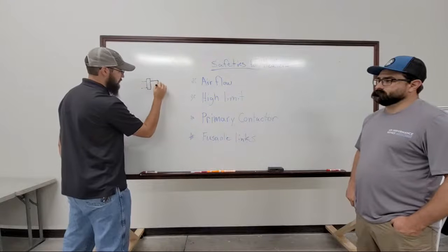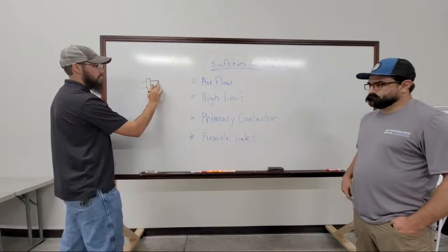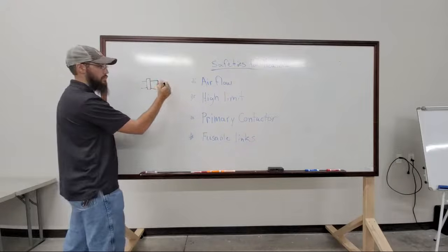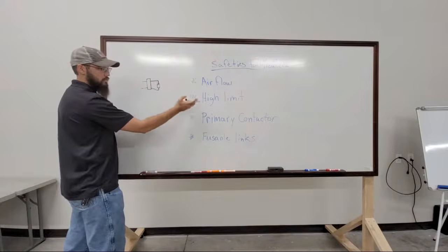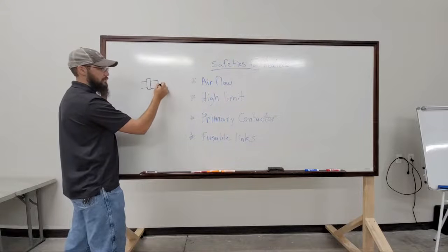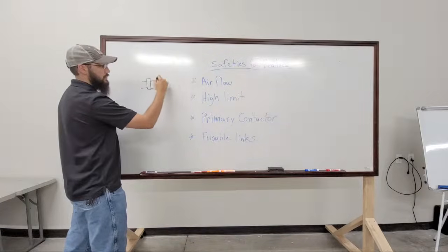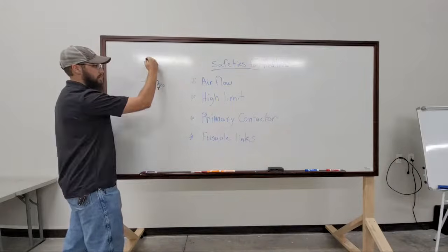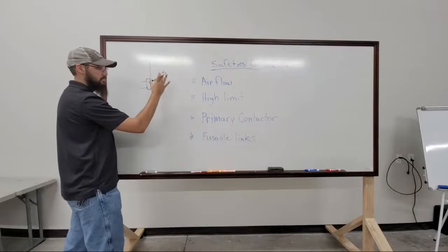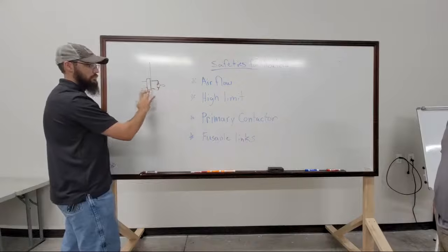It's a heat driven fuse that comes back, and this is fairly old. You're not going to see this on any new stuff, but you see this a lot on your older systems. In the same way that a normal high limit would trip, a fusible link, once the temperature, usually around 210 degrees, once the coils within inches of this fusible link in the airstream heat that link up, it will melt internally, and it will stop power flow entirely.